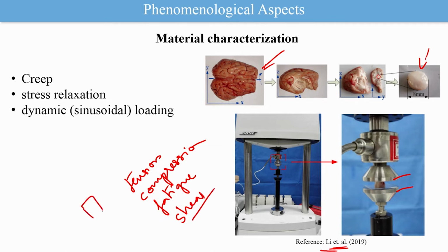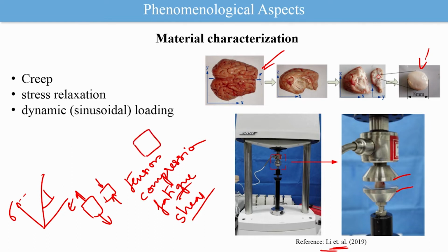In tension test, a material will be pulled, and once we pull it, we plot the stress versus strain to see what is the elastic modulus, elastic limit, all these things. And same for compression, you apply a force to compress the tissue or the material to know the behavior. Okay. You load it and unload it at very high rates to understand the fatigue. You apply the load in an angular way to understand the shear behavior of the material.